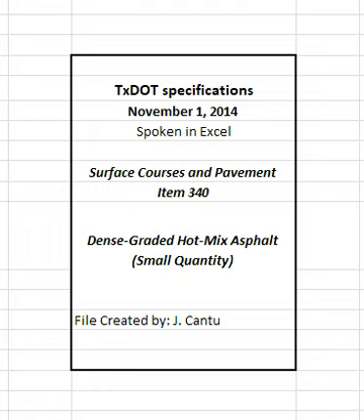Core samples, if taken, will be obtained from the center of the finished mat or other areas excluding the vehicle wheel paths. The engineer may require up to the entire lot of any mixture failing the Hamburg wheel test to be removed and replaced at the contractor's expense. If the department's or department-approved laboratory's Hamburg wheel test results in a remove and replace condition, the contractor may request that the department confirm the results by retesting the failing material. The construction division will perform the Hamburg wheel tests and determine the final disposition of the material in question based on the department's test results.